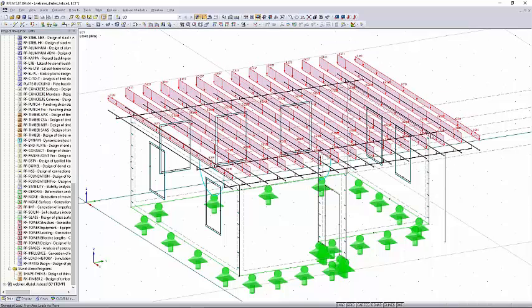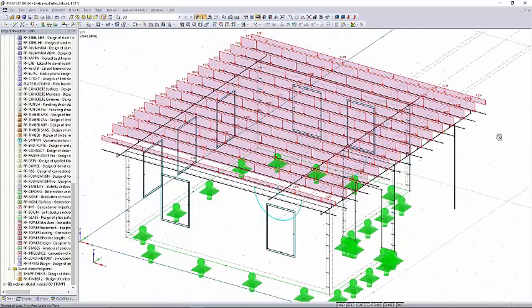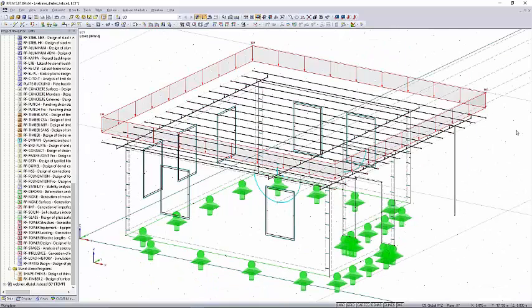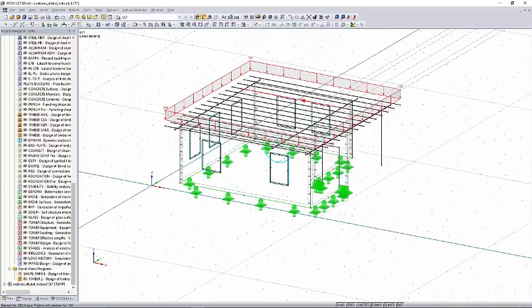If you display the load separately, you see that the load is designed just on the rafters. But you will get a nicer picture for the printout report, and the calculation is also faster if you do not separate those loads. That's why we stay on this.